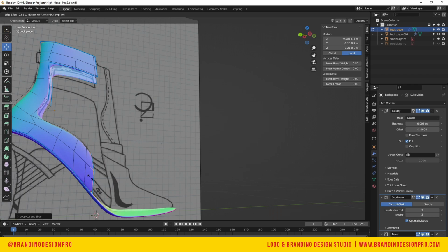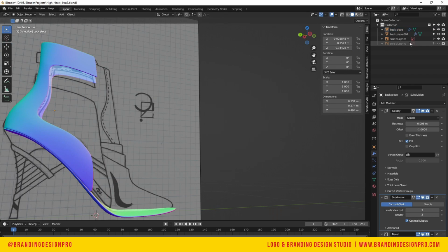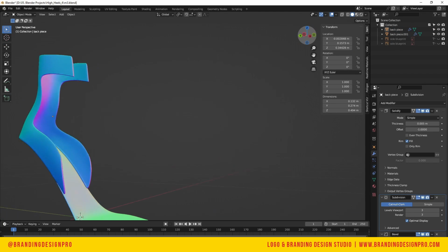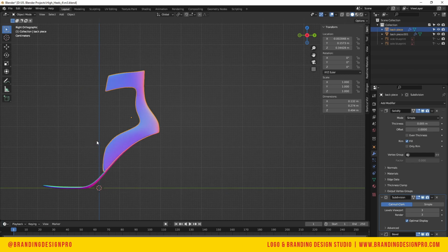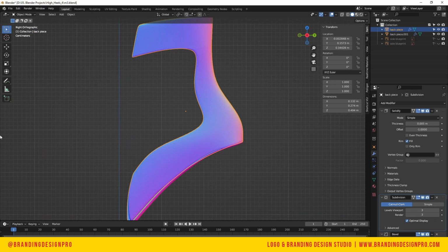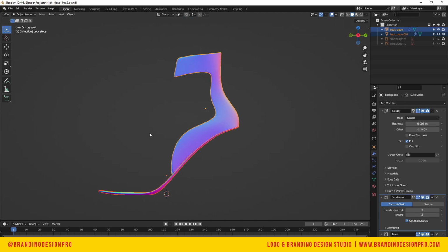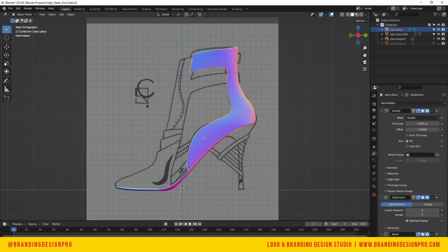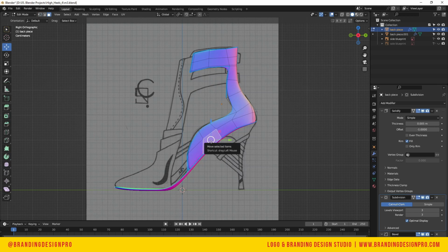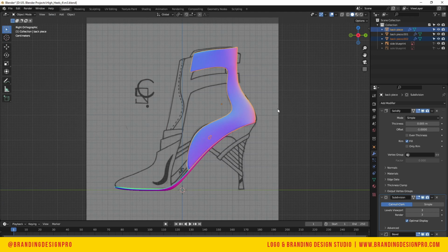Because now we don't have a mirror modifier that allows us to just automatically adjust the other side, because now we're working on an asymmetrical model. It's a little pointy towards the front right here, but that can be adjusted and corrected. So let's just move on to the next really important part. We're going to go to face selection mode, select that side panel, Shift D, P to separate it, tab out, and then we're gonna select that piece and tab in.